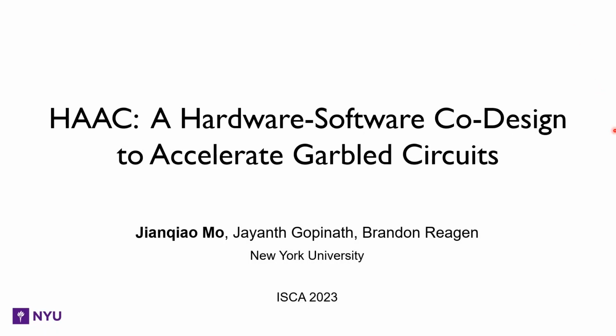Hi, this is Jianqiao. Today I'm going to introduce how we apply hardware and software co-design to accelerate Garbled Circuit for fast and arbitrary private computation. In this talk, you can see how we take the insight of Garbled Circuit as a data-oblivious program to build a novel system that streams the regular and addresses the irregularities by decoupling the program execution and memory access. We eliminate the expensive hardware with a VLIW-like compiler to enable parallel performance.